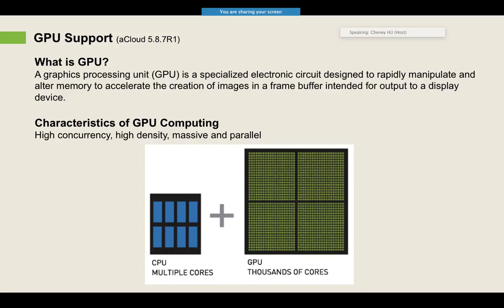And it is a very large batch of data sets. So why is GPU more suitable for those particular workloads? The difference is here, like this picture shows. CPU usually has multiple cores, clocked between 1 to 4 gigahertz, right? However, the GPU has thousands of cores, and these cores are very suitable for basic mathematical computing, for workloads like video transcoding, graphic rendering, or big data analysis.